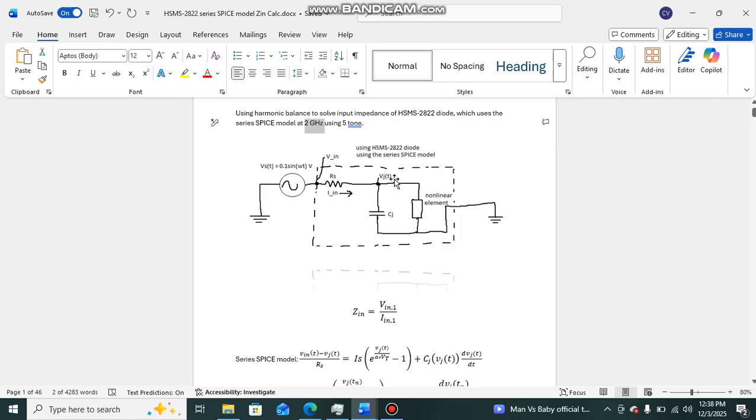Another reason could be that if you keep on amplifying further at 2 gigahertz, it would be very prone to oscillations, versus if we down convert it to 100 megahertz. So there are two types of mixers. There are active mixers and passive mixers.